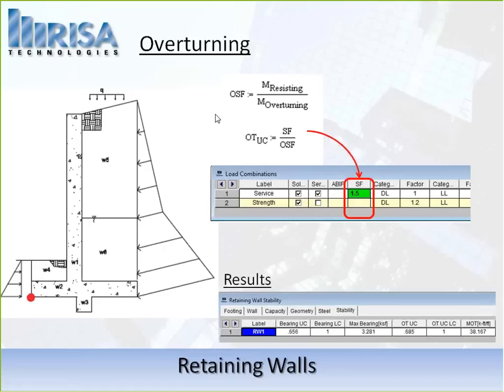for you, only on the ones that are retaining walls that are cantilevered. So propped ones, we're not going to do an overturning check because, of course, they are propped, so there's not really any overturning, they are supported by something at their top. And then for sloped backfills, the vertical component of the hydrostatic load is also going to be included, so that would be something additional in there. So you can see that.